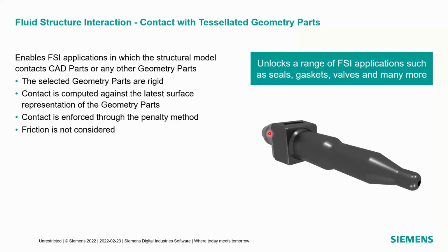So basically, this is probably best explained with the picture. This gray piece and dark black piece fit together, and there's a deformable gasket or seal between the two. And the seal squeezes the assembly, but it also serves as a check valve for the cleaning liquid in this. I think it's an automotive camera valve to help clean, I guess, camera lenses.